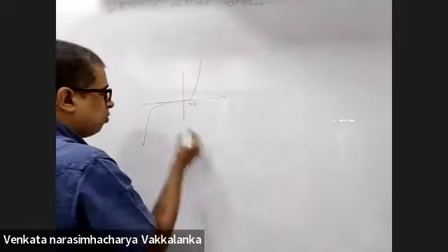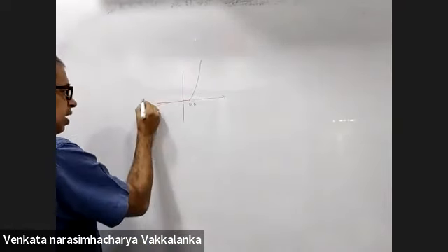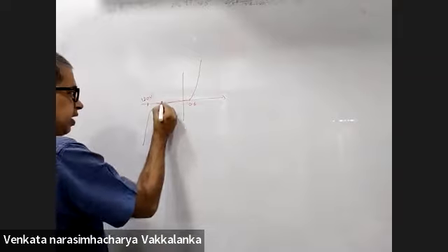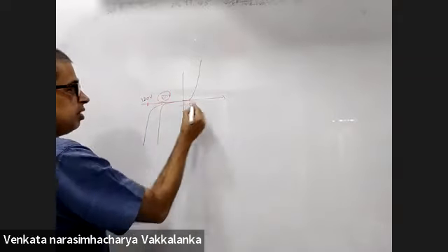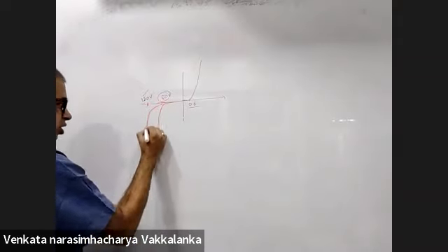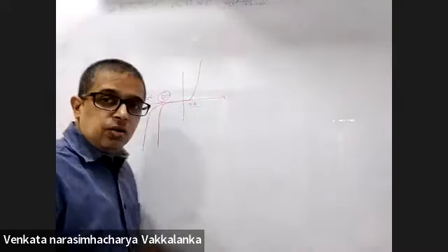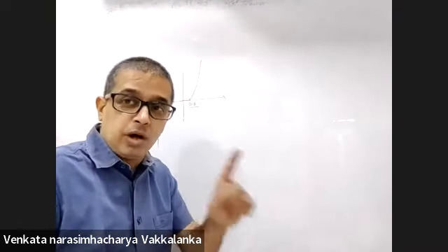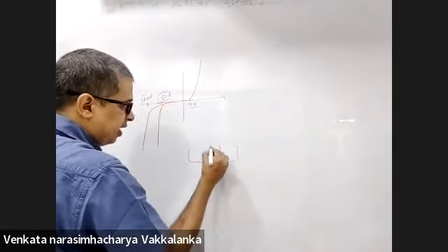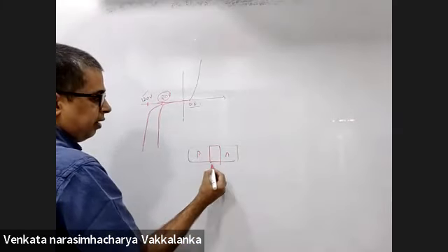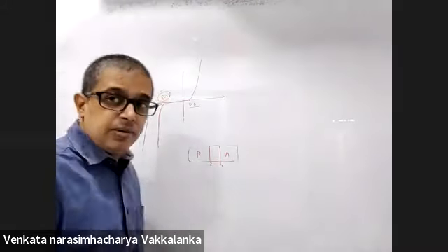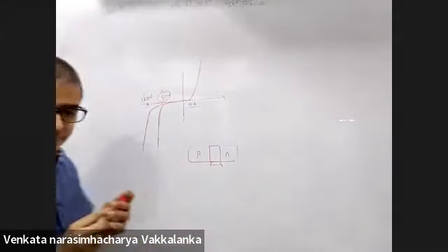So in the Zener diode, what do they do? Normal breakdown will happen somewhere at 120 volts. In the Zener diode, the breakdown will happen at 80 volts. This figure is more comfortable to use in the circuit. Neither this nor this, this is the Zener diode. This is avalanche normal breakdown. If you go up to 120 volts, there will be conduction in a normal diode. So the Zener diode they heavily dope, and decrease the thickness of P and N. When they decrease the thickness, reverse bias conduction will happen at 80 volts, and that's a comfortable value for your circuits.